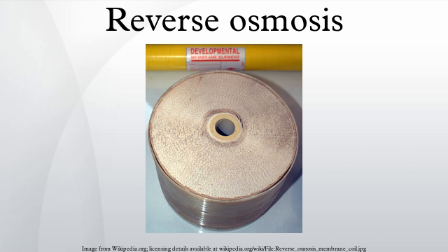The desalinated water purity is a function of the system design. Higher purity needs more equipment and more energy. Purity expressed as total dissolved solids typically varies from 100 to 400 parts per million. A level of 500 ppm is generally accepted as the upper limit for drinking water, while the U.S. Food and Drug Administration classifies mineral water as water containing at least 250 ppm.